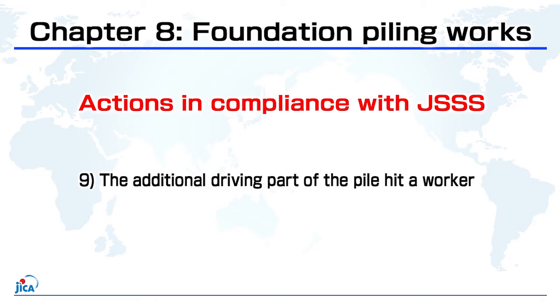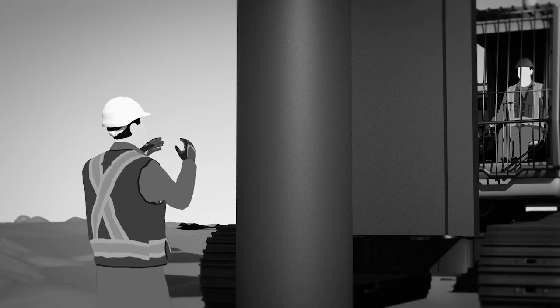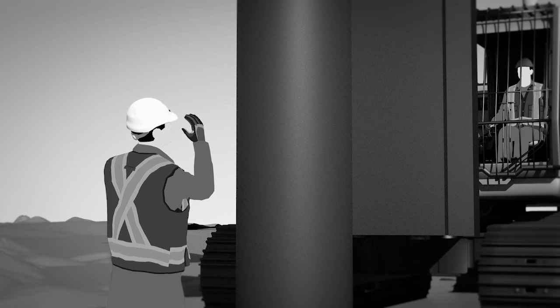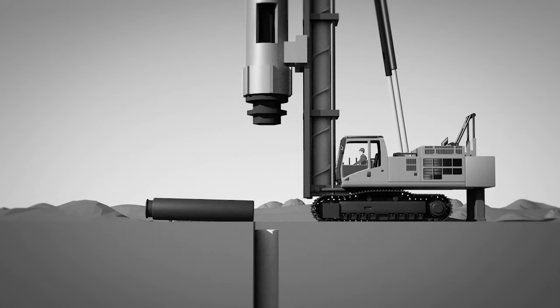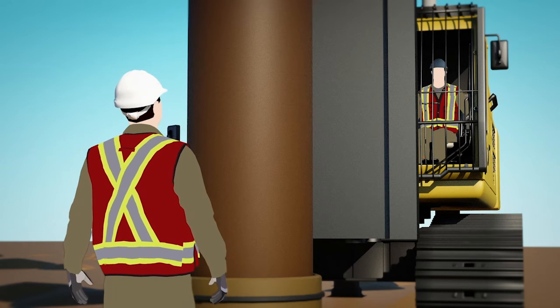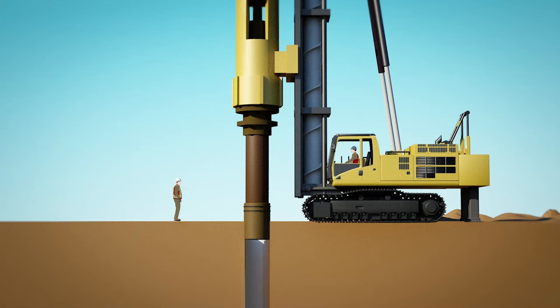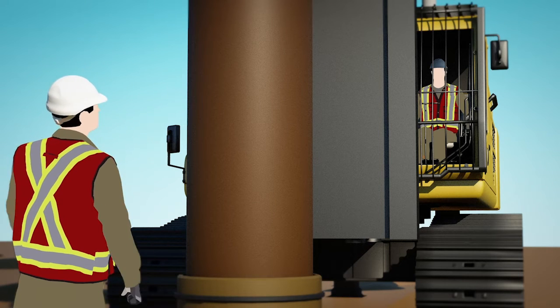When driving piles, proper methods must be used according to the characteristics of the equipment and pile material. In this case, when the follower was struck, it swayed laterally and received an eccentric impact. In addition, due to the impact exceeding the allowable force, the pile material was damaged and the cap fell. Checks must be performed from time to time to determine whether there is any misalignment between the center of the pile and the hammer. In addition, the pile material must not be hit with more force or hit more times than the tolerable limit.